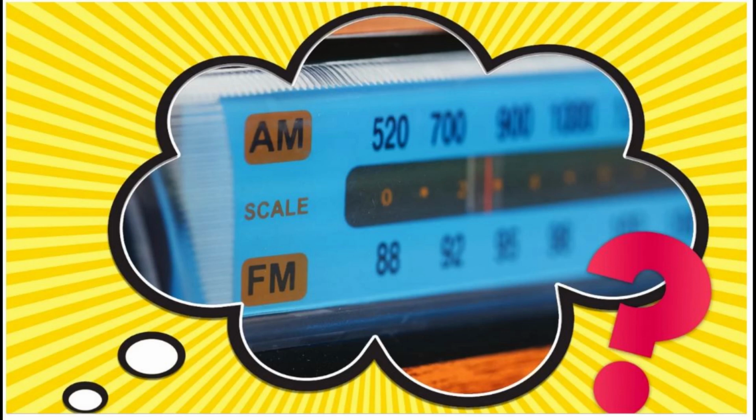Keep reading to learn about the difference between AM and FM radio technology and the National Inventors Hall of Fame inventors behind each one. How do AM and FM radio work? Every radio station sends out a carrier wave, or carrier signal, with variables including amplitude and frequency. When a station plays music or begins any other kind of broadcast, the sound waves are converted into electrical signals that reach our radios via the carrier wave.